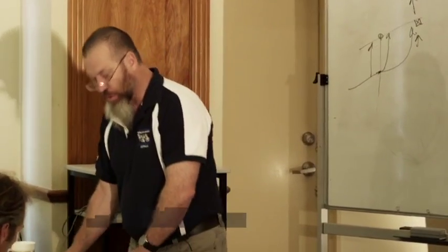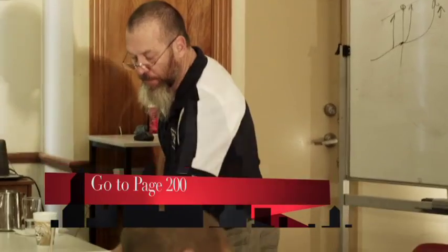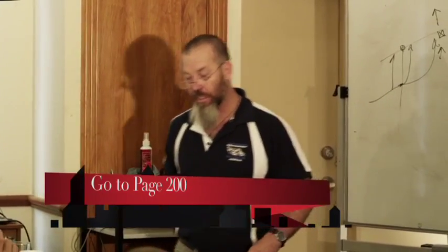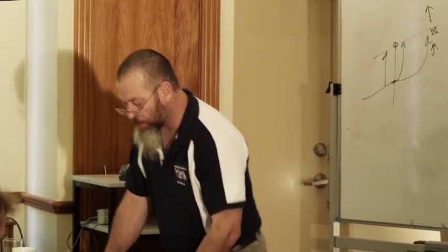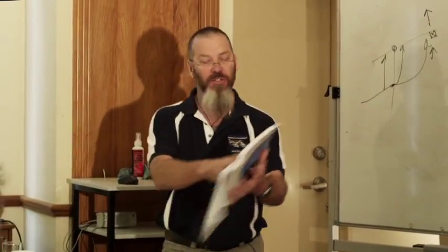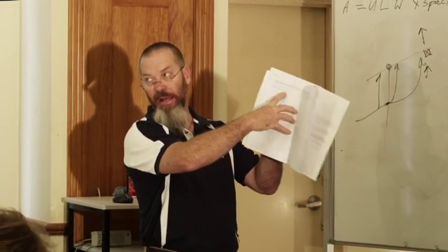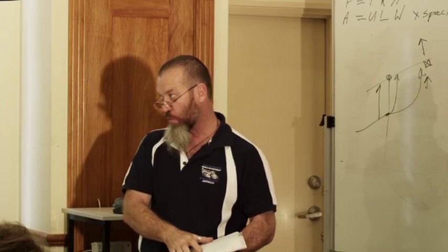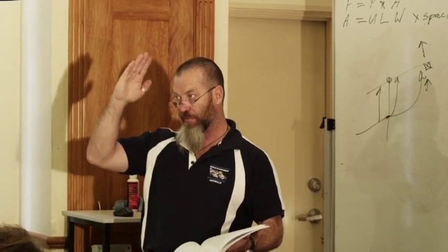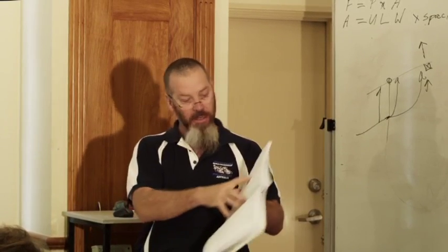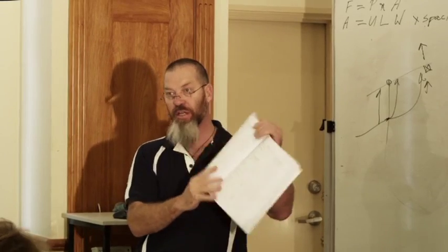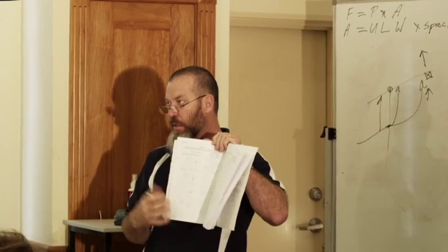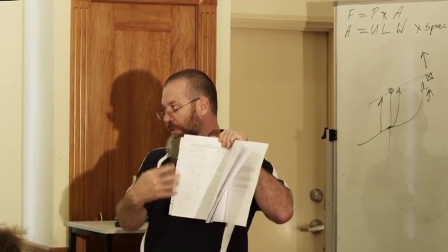Can you go back to page 200 in the new book? And this heading basically reads, or very similar to what we just looked at, it says uplift capacity of rafters and truss tie-down connections. And then this part here, that little line there, it says rafters to wall frames or floor frames. And that'll be floor frames in an attic roof situation. But that's the table we should be using. And you can see in the picture, when you look at the pretty pictures, which builders are prone to do, you look at the pictures and it actually tells you which one.